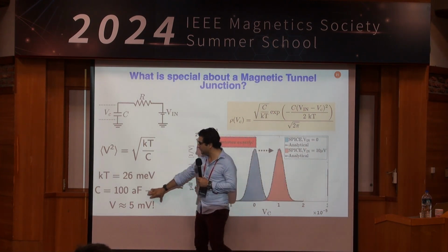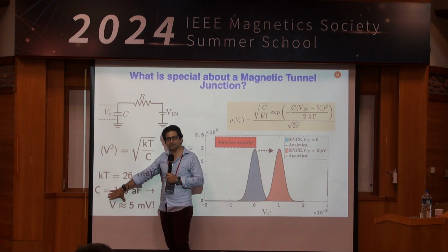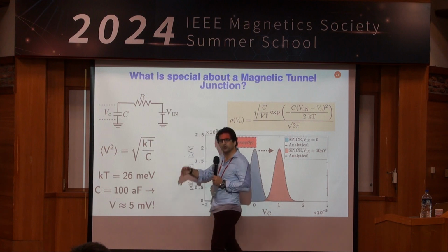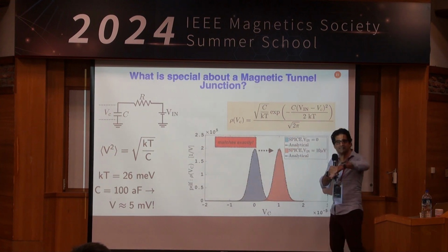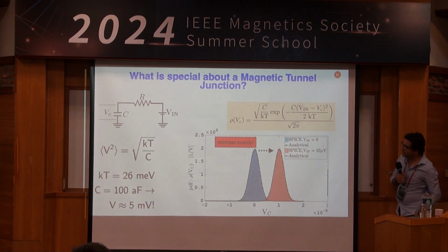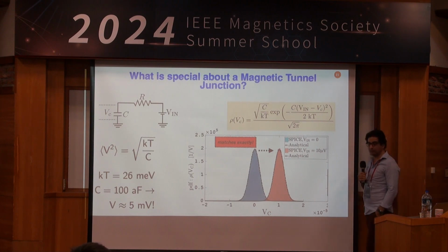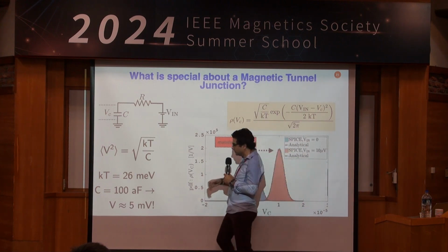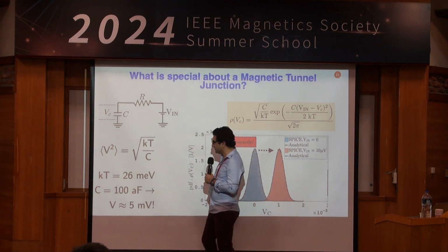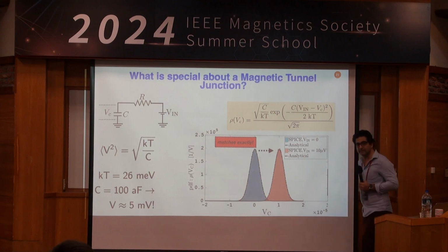But this is about the gate capacitance of your transistor. A minimum width transistor would be of the order of something like, I mean, it's obviously a function of voltage and whatnot, but it changes between 100 and 400 attofarads. And it's mighty small. It's really small. In fact, it's incredible. I'm not sure it's easy to measure such capacitances.